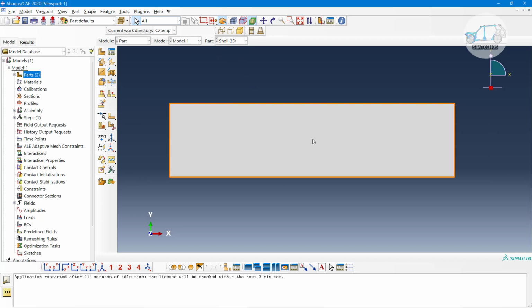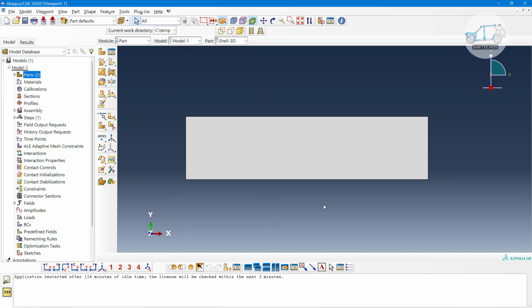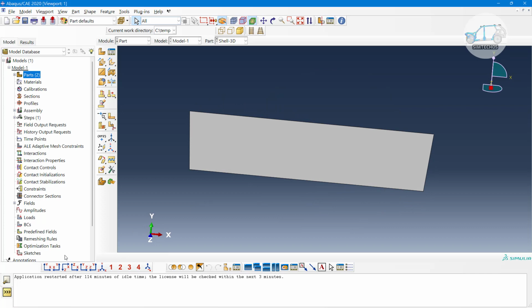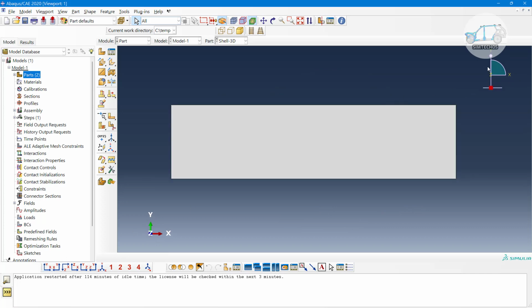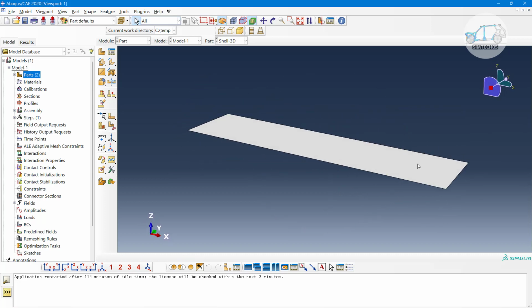See, this cell 3D component, that we created using the 3D options, then cell and planar options, can be bent along the planar direction. The plane of the cell is x and y. It can be bent, it can be stretched in plane direction, x direction, y direction, as well as out of plane direction, and the out of plane direction is z direction. Here you can apply load and this can be bent.